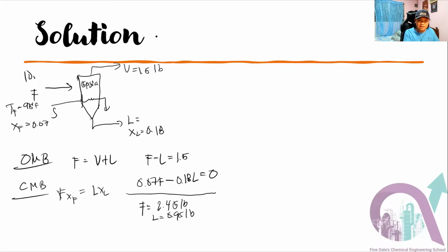So we have our 5 psia pressure, diba? Just multiply it by 6894.8 and then you can get the pascals. This is the conversion factor from psi to pascal. Then you have the temperature of the evaporator, ba?